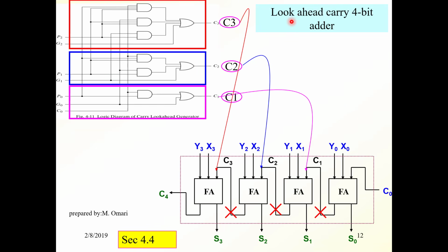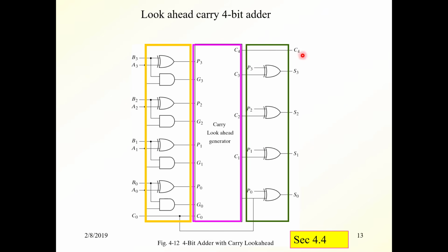But there is this look-ahead for the carry at the final circuit for the new adder that resolved the problem of the delay, and this is called look-ahead parallel adder. Look here to see the look-ahead generator in between the inputs, the direct inputs X and Y, and here we name them A and B, and the output.